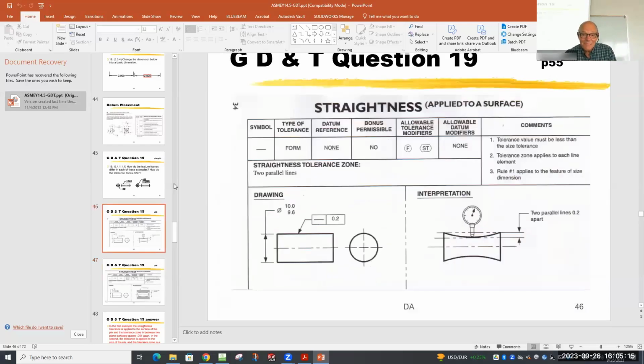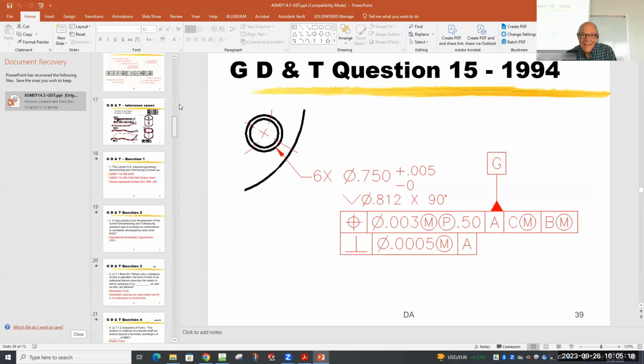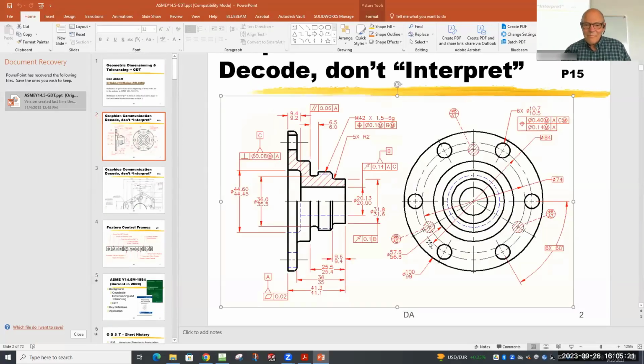So now we go back here and I look at this. Max material condition is when the hole is as small as possible. If I try to put that over a pin, in other words, I try to put it over the thing it's supposed to go over, and I've got one here that will not go. I can't get it on there. And I measure this, and it measures 44.45. I'm going to bore it out to 44.5. It's still going to be the right size, and then it's going to go over there. So what I do is move away from maximum material condition to something that still is the right size, still within the tolerance zone. But when I make it bigger, now it's more likely to go together.